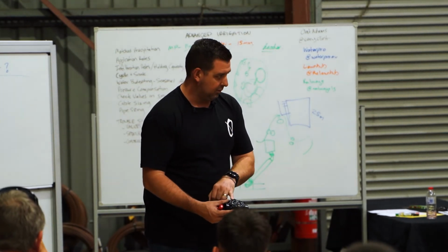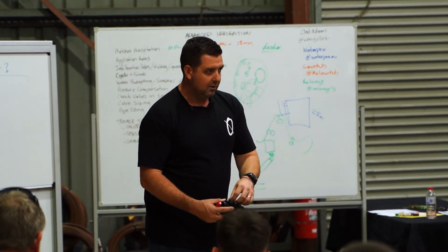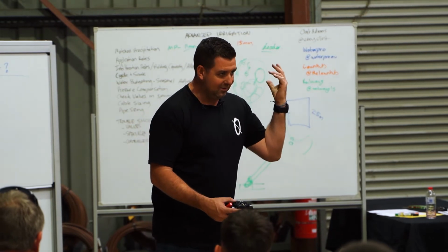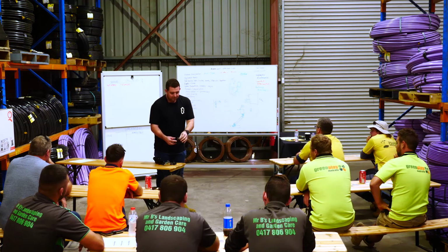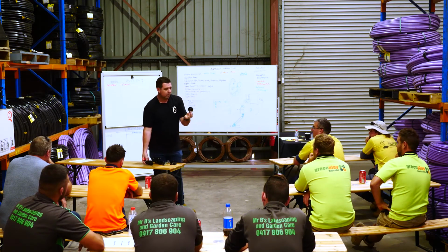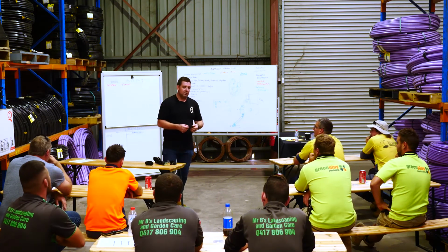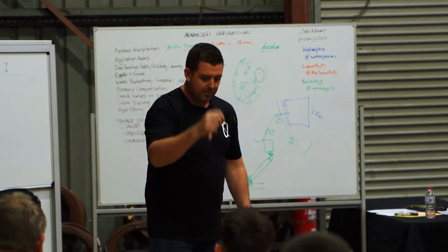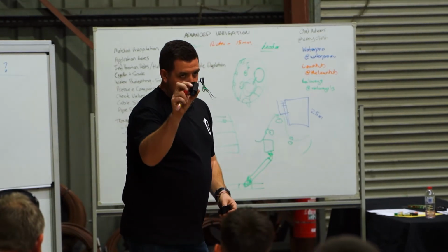The 205 is a good one. I don't know if you've ever replaced those. You open a 205, boing, spring's gone. That's the only thing that you'll replace. And when I say it's the only thing, 99% of the time it's a diaphragm. It's really rarely ever a coil.